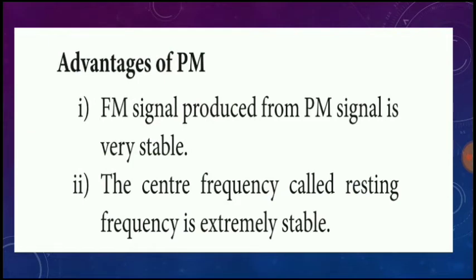So advantages of PM. Which is advantages of PM? The FM signal produced from a PM signal is very stable. Frequency modulated signal produced from phase modulated signal is very stable, and the center frequency, called the resting frequency, is extremely stable, right? So these are the advantages of phase modulation. This is also another 2 mark question.